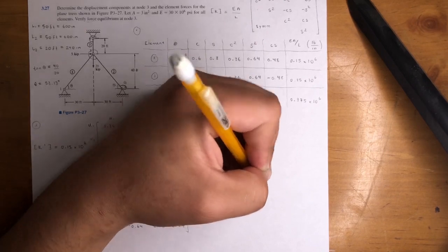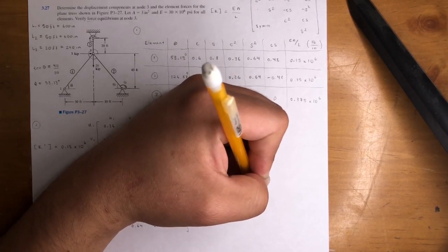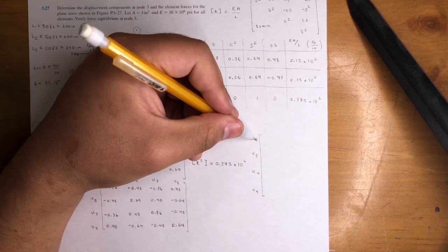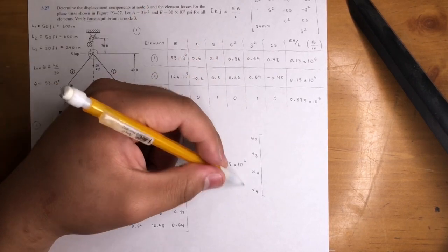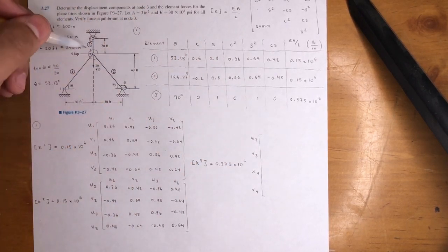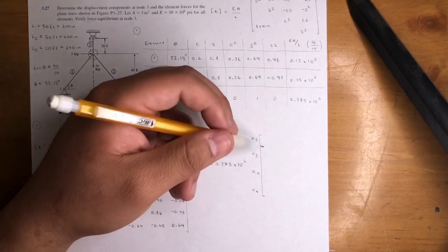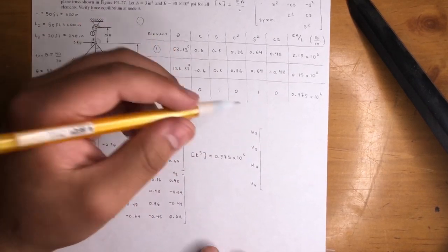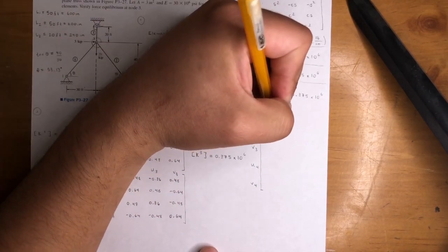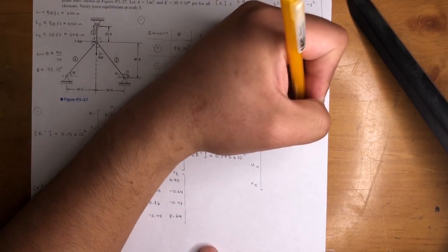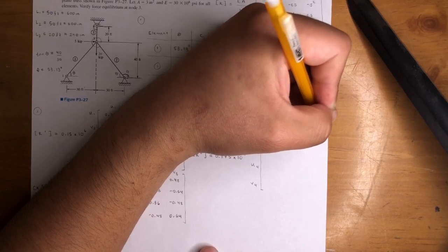the angle from small node to big node, because I just like to stay consistent. The small number here, the big number here. I would have had to switch these two if I used angle 270, remember? But I mean, technically it's still right. Just I like to go from small number to big number. And U3, it's gonna be a little tight here, and there we go.